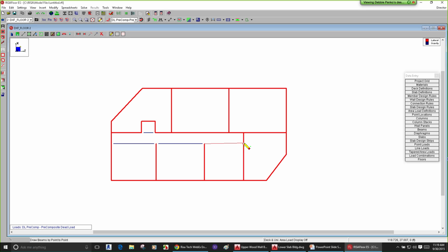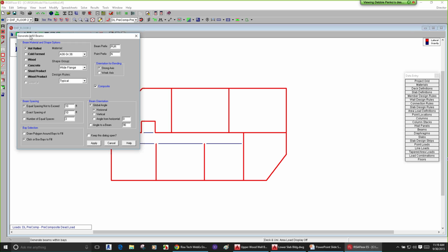So this would be more like apartments. I've got some apartments across the structure. I'm going to put some infill framing in the different directions, all in these different bays. And then I'm going to just draw this off here. So the program's really smart about infill framing. Sometimes in some of these little areas you can draw across and it will help you to infill a bit. So I'm going to use the infill framing next.